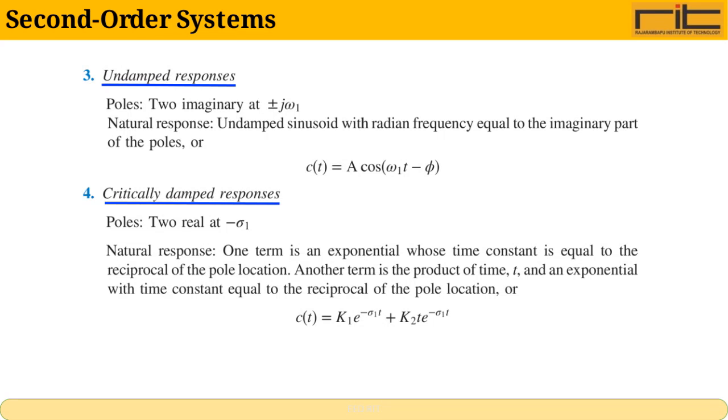These systems are characterized by differential equations where the highest derivative is of the second order. What makes them particularly interesting is their dynamic behavior, which includes oscillations and complex responses that you don't see in first-order systems. Understanding second-order systems is crucial because they model many real-world processes, from mechanical vibrations to electrical circuits. Throughout this section, we'll explore their natural frequency, damping ratio, and how these parameters influence the overall system response. This will give us a solid foundation for analyzing and designing more complex systems effectively.